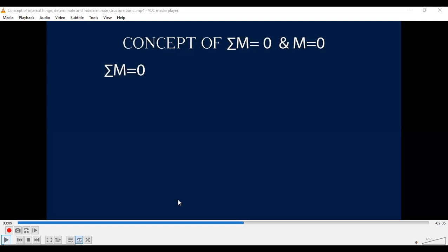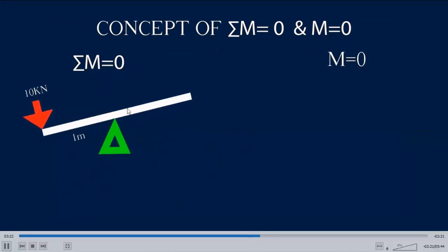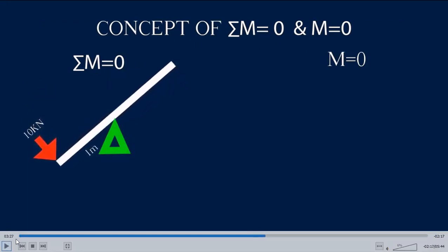Here's the thing. Get this concept. This is a continuous beam, right? It is continuous over here, so that means at this point, sigma M is 0. The moment at that point, if you sum it up, is 0. If you load it, it bends like this. It keeps the continuity, it keeps the straight line. So it's continuous. The relative rotation is 0.